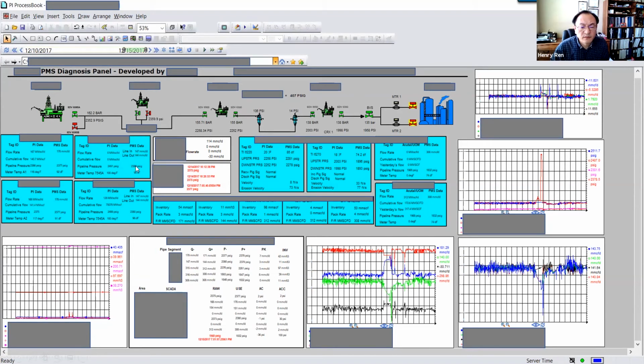If you talk about the virtual sensor, basically all those PMS data are virtual sensors, and all those are virtual values, and also velocity is an engineering parameter. Erosion velocity is critical. Okay, they monitor it, okay? They do not want to violate it. And you can see the erosion velocity is way below the limit, which is good.